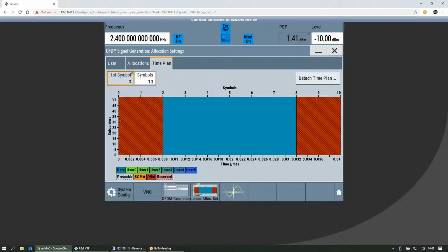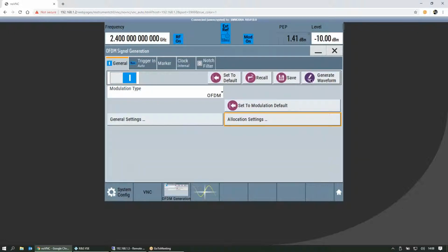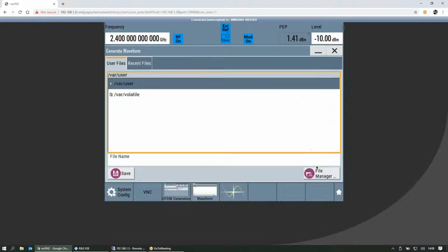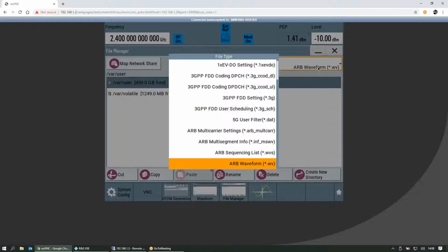Since the demodulation needs to be aware of this framing structure here. It needs to know the number of subcarriers, needs to know which subcarriers are occupied, where the pilot is, so it can correct for imperfections in the channel. And so all of that is then going to be available to us from a pre-generated XML configuration file.